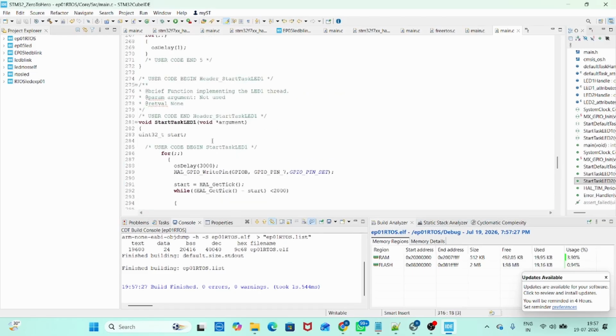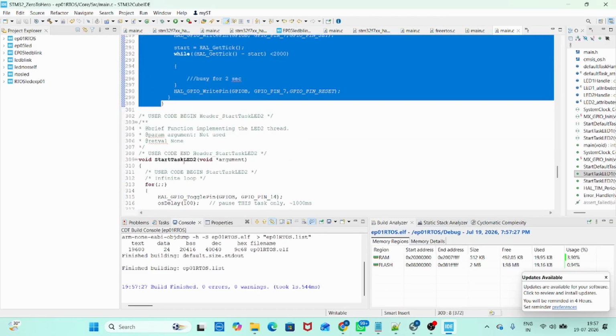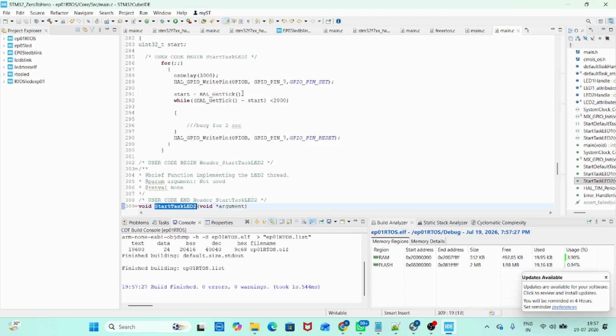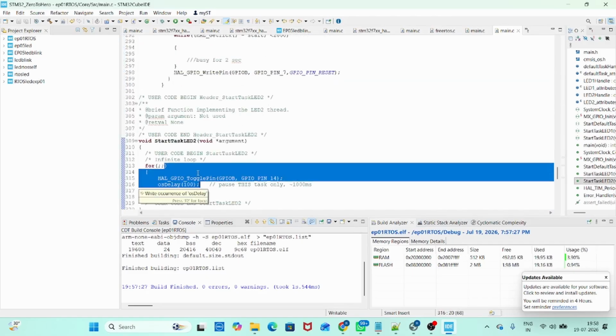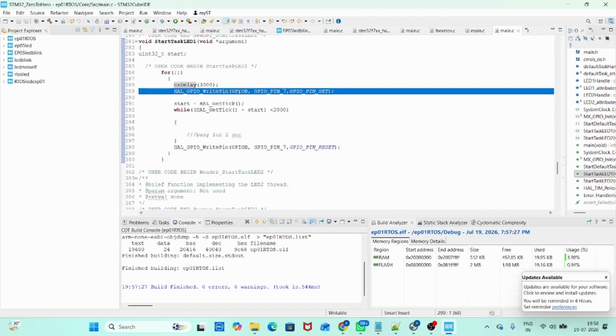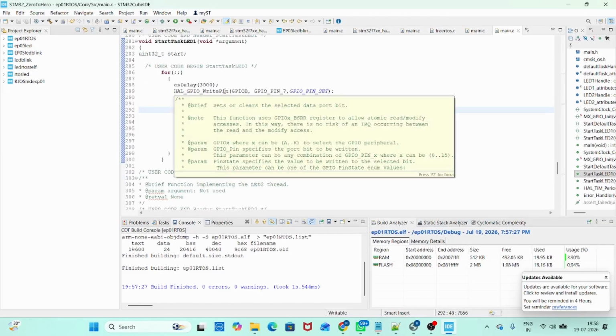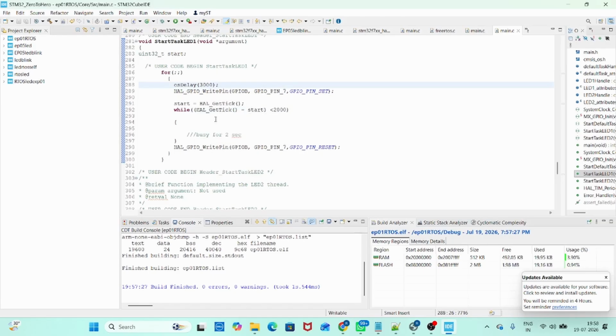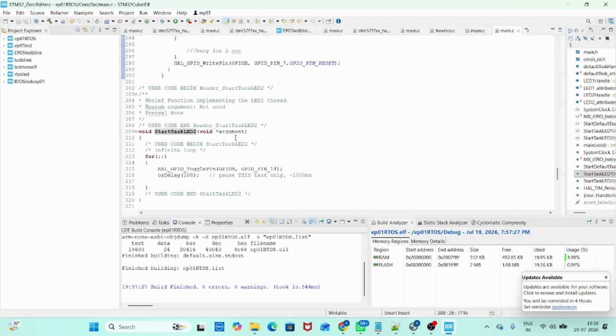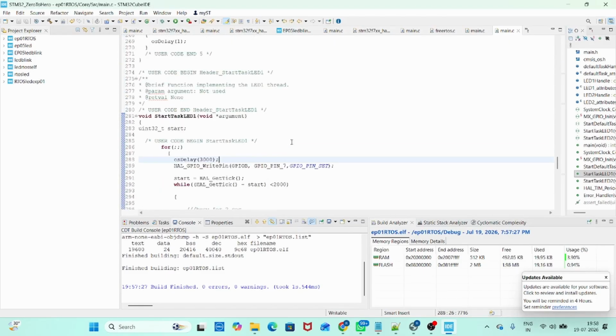As per our first episode, first it will execute this task, then it will execute this task. Now with preemptive scheduling, after 3 seconds, this LED will have been continuously blinking, but then this high priority task will start executing. It will not allow this function to execute until this task finishes. And what we are doing in this function is intentionally setting a 2 second delay. So after 3 seconds, for a continuous 2 seconds, this function will take the resources. Because the high priority task is trying to execute something, the operating system will allow this task to execute and block all other tasks. Again, here we are simply using 2 tasks, but even if we have many tasks, it will only and only allow the high priority task first.